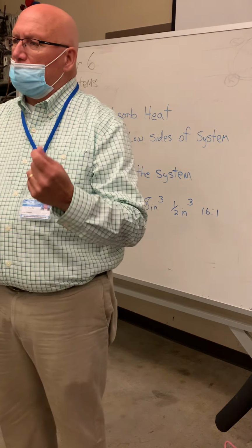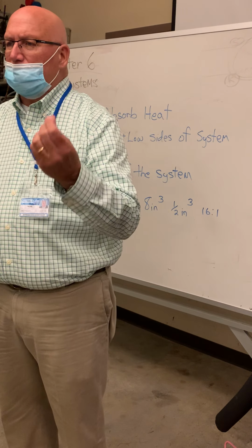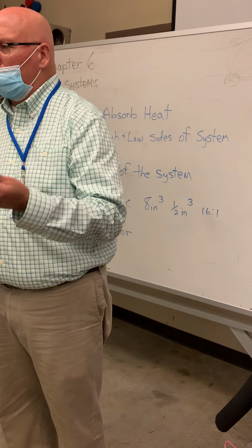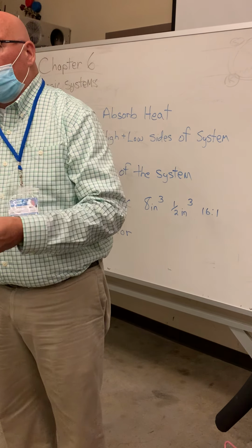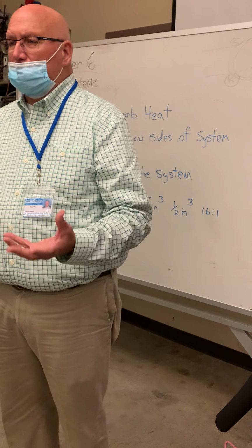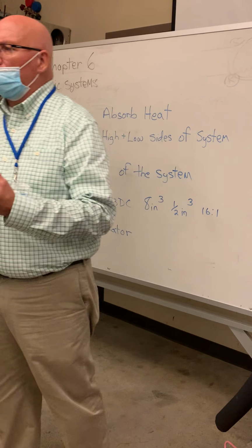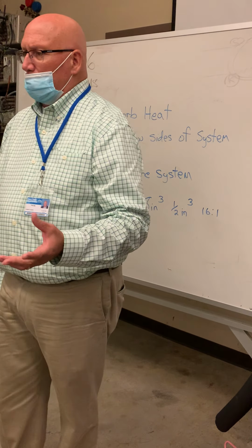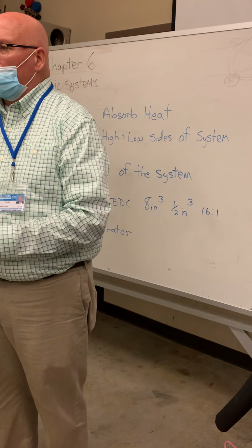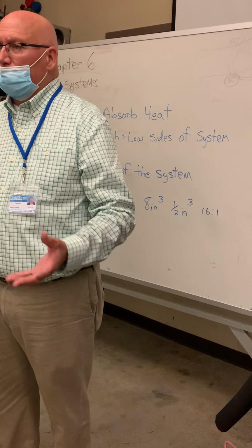When you take your gauges on and off, you're going to have a little bit of that refrigerant oil on your hands that you'll have to wipe off. The oil travels throughout the system, and it's a good thing that it does, because there are certain things that we want it to lubricate. But we don't want too much oil in that system, because if there's more oil than what we want, what do we have less of? Refrigerant.